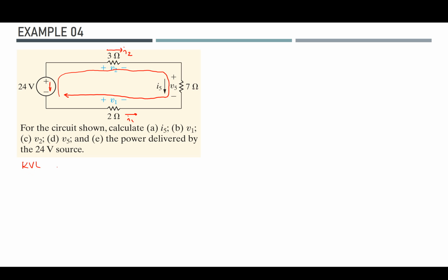So I have the voltage source, but I'm rotating in the opposite direction. As you see, I'm rotating clockwise, so I'm opposing it. I see the first negative terminal, so minus voltage source. Then I come to this resistor, which is R2, let's say, because it's denoted with the index of 2.